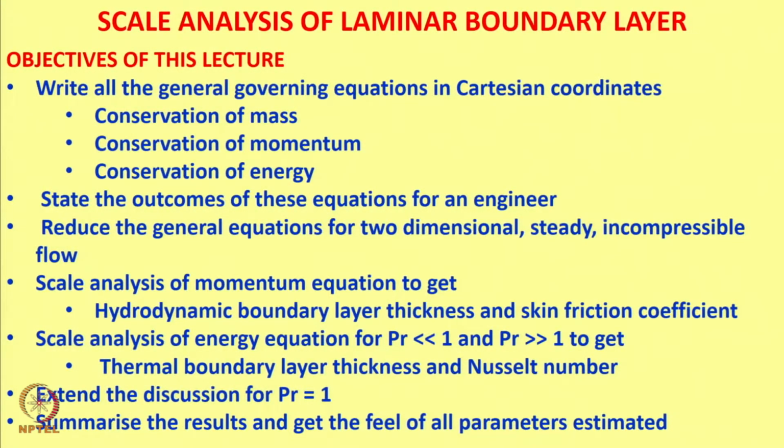The objective of this module is that we will recap conservation of mass, momentum and energy, state the outcomes of these equations for an engineer, reduce these equations for two-dimensional steady incompressible flow, and do scale analysis of the momentum equation to get the hydrodynamic boundary layer thickness and skin friction coefficient. We will further do scale analysis of the energy equation for Prandtl number less than 1 and greater than 1 to get the thermal boundary layer thickness and Nusselt number, and extend this discussion for Prandtl number equal to 1, and we shall summarize the results and get a feel for all the parameters we have estimated.